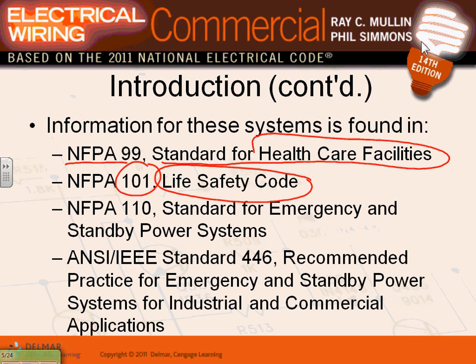Because the code doesn't tell you where do you need the egress signs and the exit signs and egress light. It tells you if you need them, this is how you wire them. The same thing in the healthcare facilities, guys. If you need them, this is how you wire them. So these are more different articles that talk about it. NFPA 110, standard for emergency and standby power system, how it works and how it's put together and so forth.